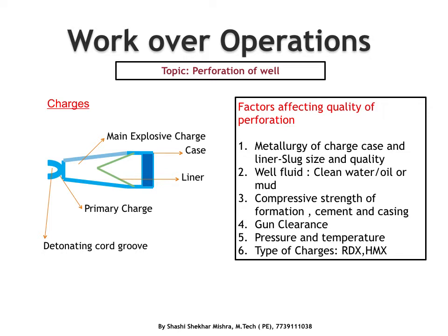Then comes the fluid under which the perforation is being done. If we perforate with clean water or oil, it has a better flow index after the perforation than with mud. Mud-based perforation causes plugging of the perforations and needs to be cleaned out later to make it flow.